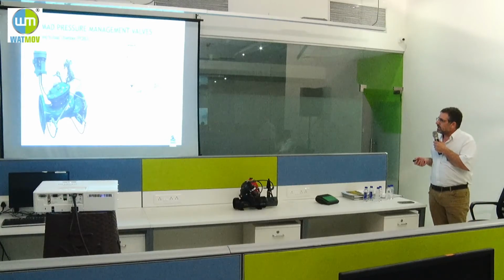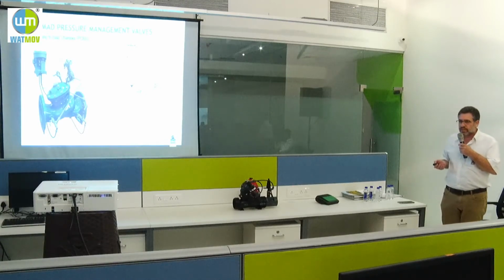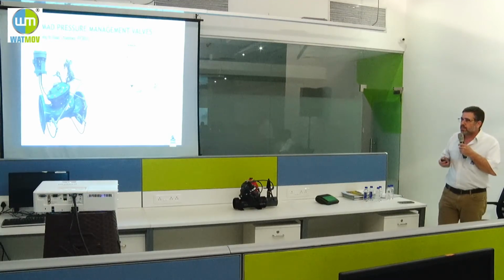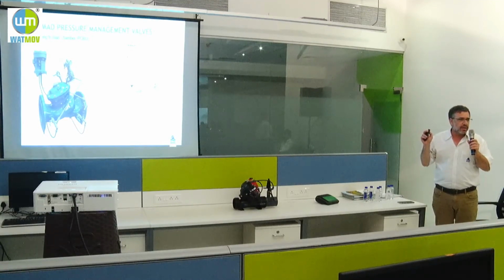Also in the other direction, it's connected to the pressure sensors upstream and downstream of the valve. And if I have a water meter, the unit is connected to the water meter as well. So I get all the information in real time on the cloud, what is going on. So when I said that this unit can work as a standalone, I put it on the main valve at the entry of this pressure area, and I control it like that.